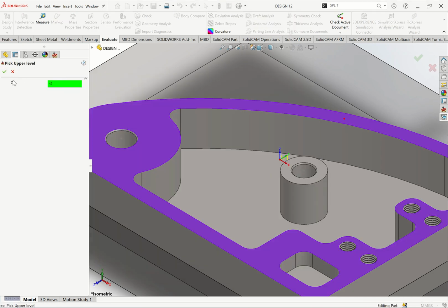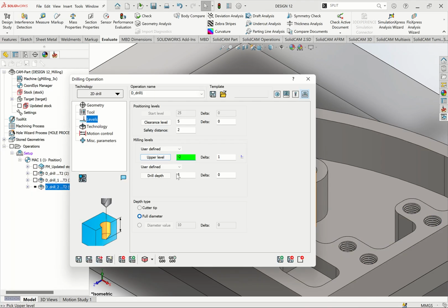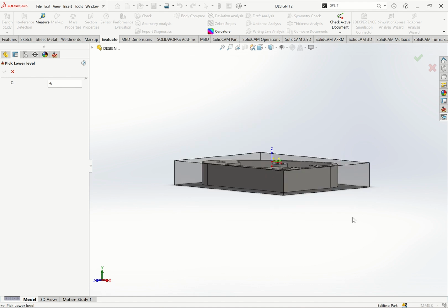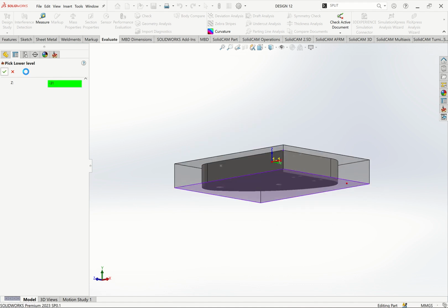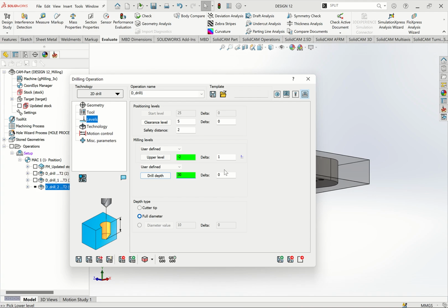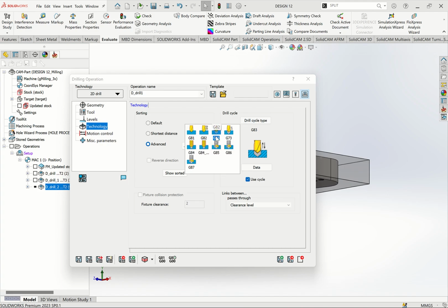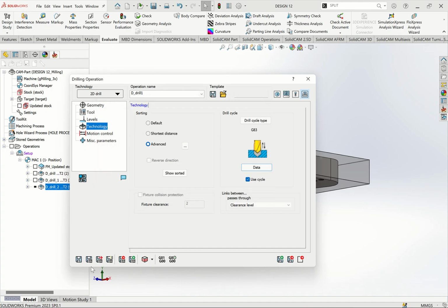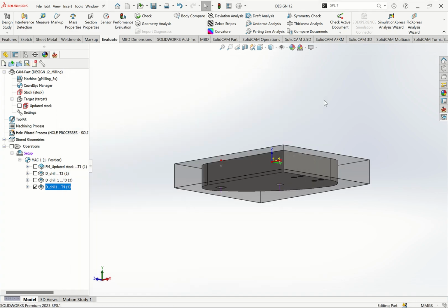You're using this upper level, same. Pocket depth, you're using 31, so you can click depth, then you pick the depth here. This is our depth, okay. I also want to exit by -3, okay. Then full depth technology, I'm using PEC, so I can use PEC. Then I change here data, I can put here 4, okay. Then calculate like that. So you have this.